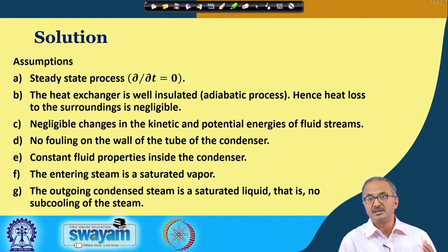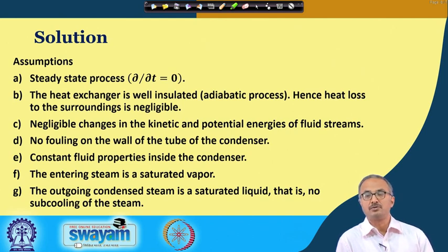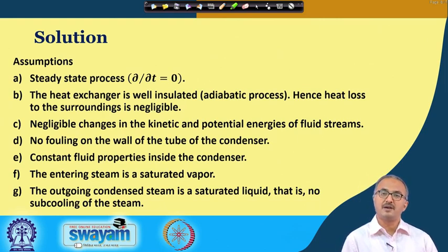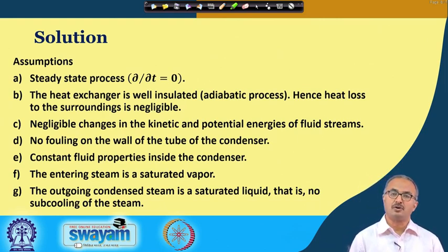If we have superheated steam, then the superheated steam should first be converted to saturated steam, and that will involve some loss of sensible heat. And again, if the saturated liquid is getting converted to subcooled liquid, again we have to release some amount of sensible heat. So, both these sensible heat effects are neglected.